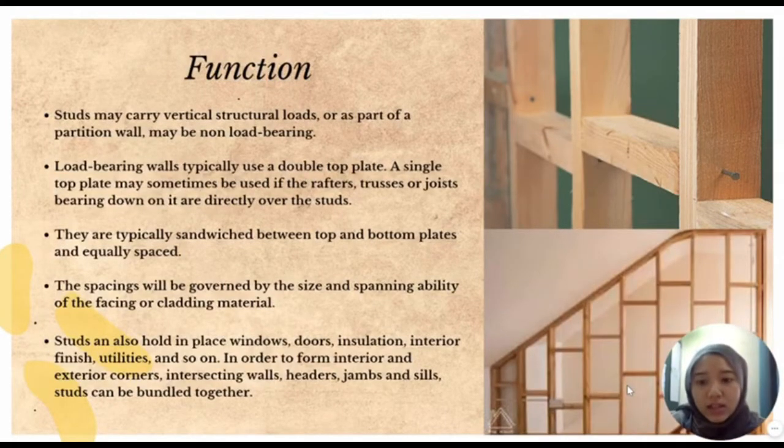The spacings will be governed by the size and spanning ability of the facing or cladding materials. And lastly, studs also hold in place windows, doors, insulation, interior finish, utilities, and so on. And in order to form interior and exterior corners, intersecting walls, headers, jambs, and sills, studs can be bundled together.